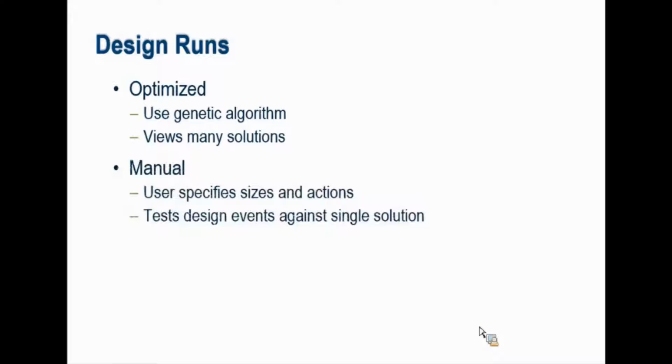So those of you with WaterCAD, you could see this run in a manual way, but without the licensing in WaterGEMS, you wouldn't be able to run it in the automated fashion to come up with multiple solutions. With the WaterCAD side of it, you would be selecting the diameters, and it would calculate the cost for you just for that selection that you manually made.